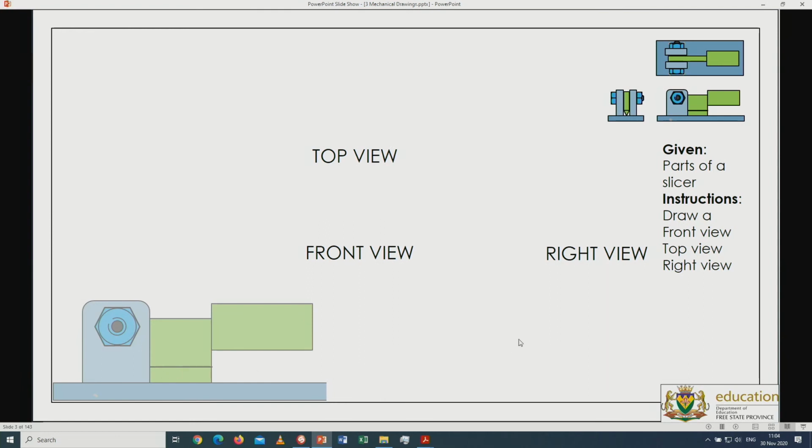I know if I place the front view on the sides, on the edge of this frame, it will fit in up to that point over there. I know I have to do the right view, so the width of the right view, or the depth of this drawing, in other words, will fit in from this corner or frame line.